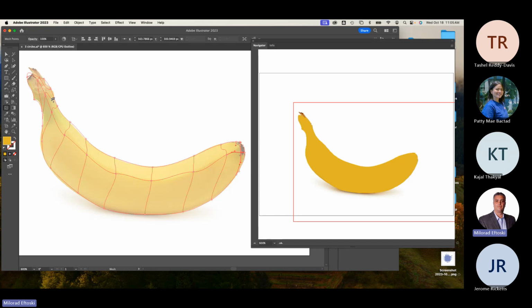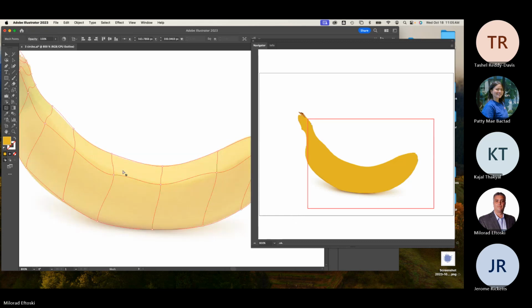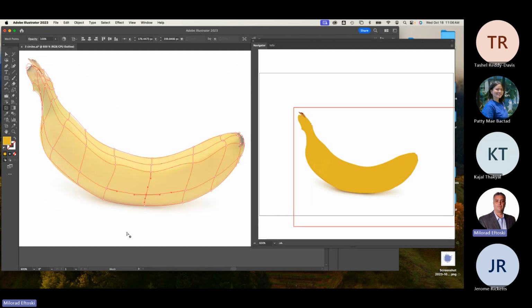And then I'll do another one over here. Watch this. Because it did this path. I did the horizontal. If I do the horizontal path, it'll create a vertical split. But if I do a vertical path, any one of these vertical paths, you know what it's going to do? It's going to give me a horizontal split, which gives me the leverage of doing the blends now. I'll do another one over here. You see? But the only reason why this works so nice is because the way I did it. It's like an art form by itself. I was very careful how I orchestrated my positions. So you have to take your time with this, basically.